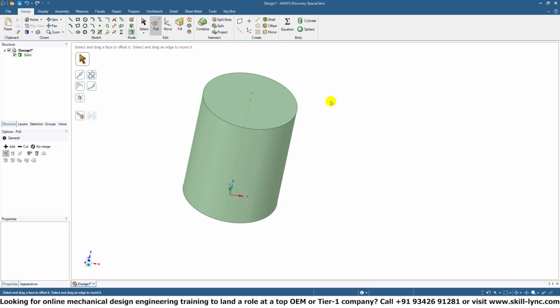You can export into a file type which is called STL, and that's mainly used in 3D printing because it just gives the dummy geometry, with just the exterior dimensions, without any of the relationships between the geometry and the calculations of how that geometry was created. So by removing some of that geometrical calculation and computation, you can save quite a bit of space in your model.